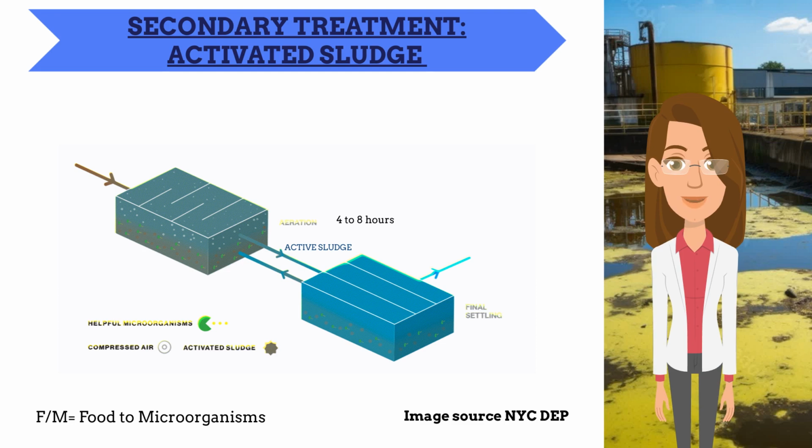The microbial biomass produced in the aeration tank must settle properly from suspension so it can be either wasted or returned to the aeration tank. Moreover, good settling occurs when sludge microorganisms are in the endogenous phase, which occurs when carbon and energy sources are limited and the microbial specific growth rate is low. This explains why a lower F/M ratio results in more efficient treatment. Additionally, poor settling may be caused by sudden changes in temperature and pH, absence of nutrients, and presence of toxic metals.